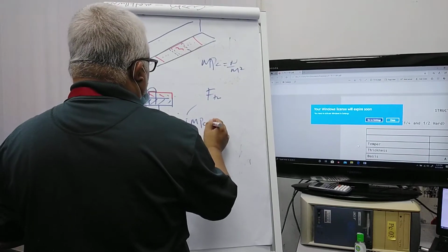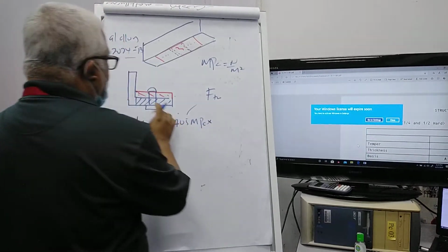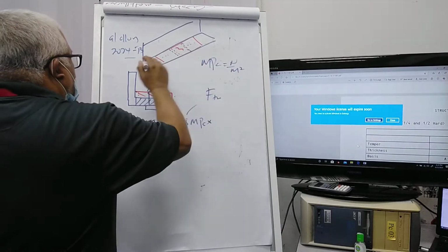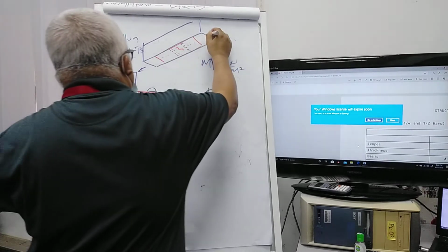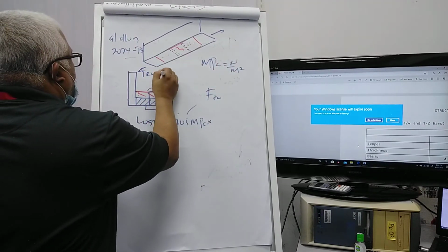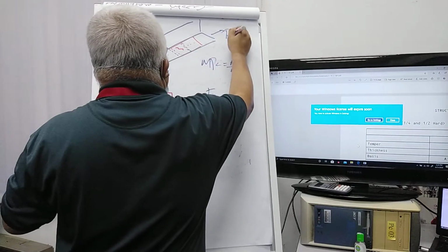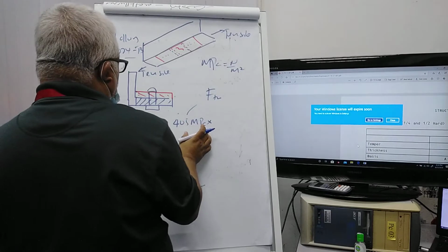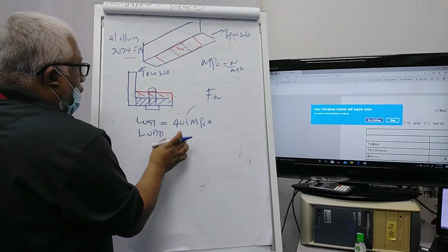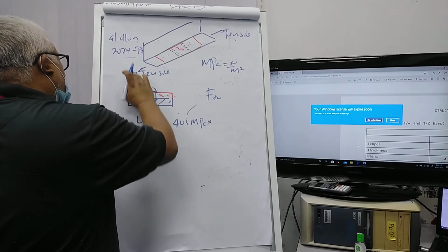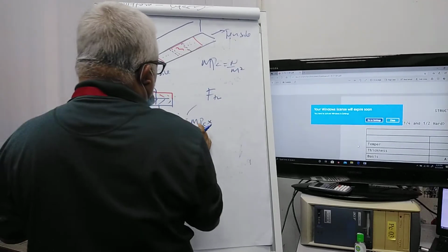So now we have to multiply by the cross sectional area, because we're talking about the load applied in the axial direction. So here it is tensile. We lost the ability to carry the tensile load, because we lost this area. So only this area now is fully functioning. And then how much is lost?